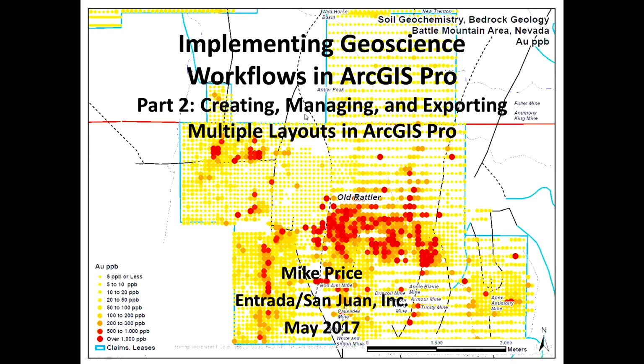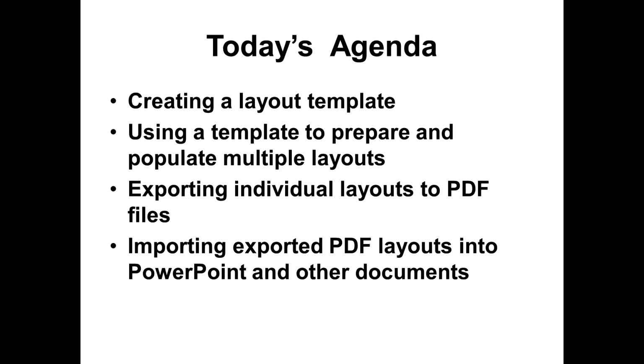This is part 2. This is where I'm going to teach you how to create a layout template and then clone that and create at least 5 more layouts for this particular project. So you learn how to create the layout template, you use the template to prepare and populate these multiple layouts, and then from there it's quite fun. You export these to PDFs or to other graphics, and then you can import those into PowerPoint or into a presentation report. And the steps are pretty simple.